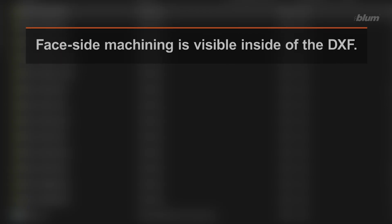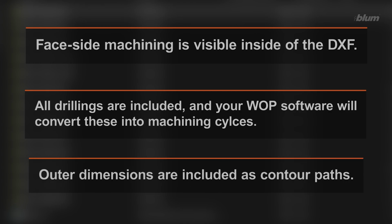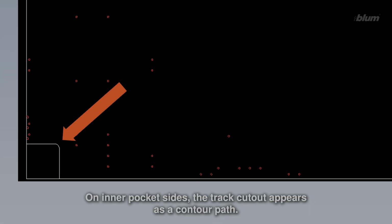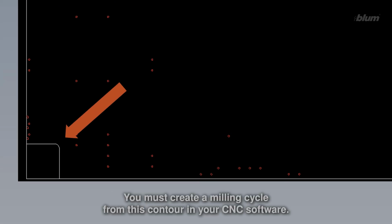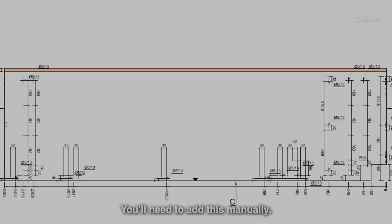Face side machining is visible inside of the DXF. All drillings are included, and your WOP software will convert these into machining cycles. Outer dimensions are included as contour paths. On inner pocket sides, the track cutout appears as a contour path. You must create a milling cycle from this contour in your CNC software. The rabbet for the back panel is not included in the DXF geometry. You'll need to add this manually.